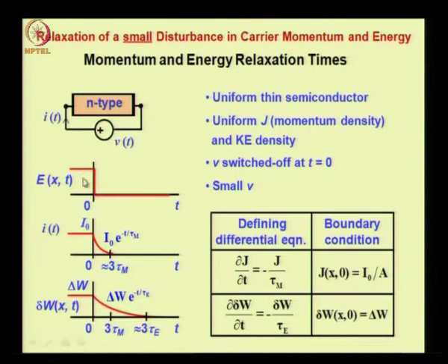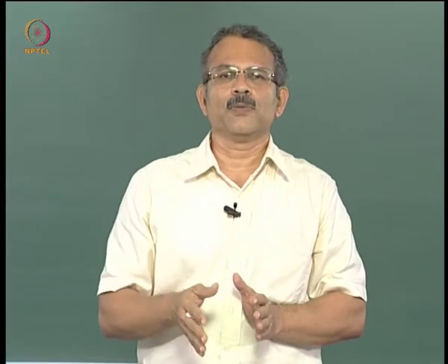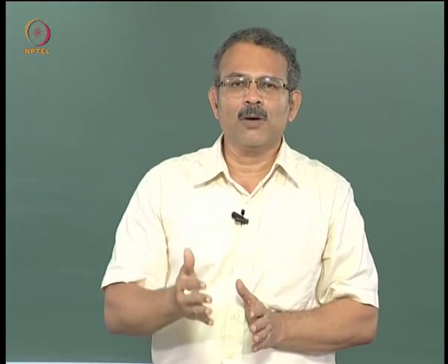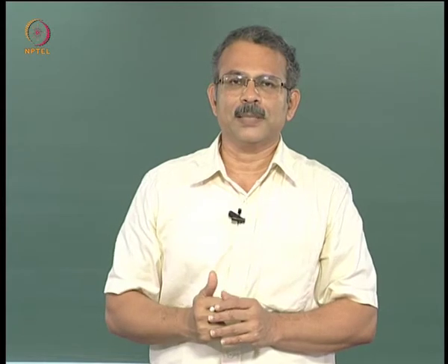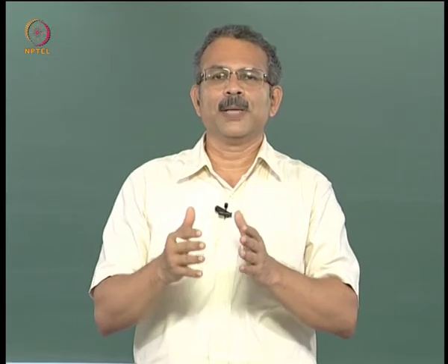Now what we find in this situation is that the current I will decay exponentially as a function of time. You might imagine, if you did not know the concept of momentum and energy relaxation time, that the moment you switch off the voltage the current will abruptly fall to 0. No, that is not what is going to happen. The current is going to decay to 0 over a time period which is 3 times the momentum relaxation time.